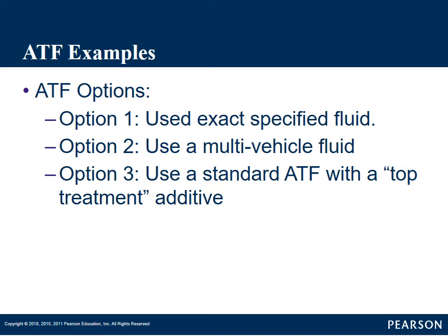As a matter of fact, in most shops they have a chart. This vehicle should take this fluid, and then what happens is, and this is where we're at now, option 2: will my multi-vehicle fluid cover this vehicle? This is what many independent repair shops do, is they use a multi-vehicle fluid.